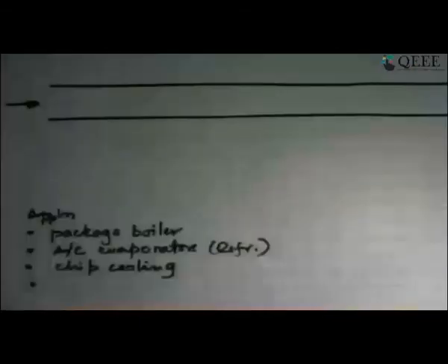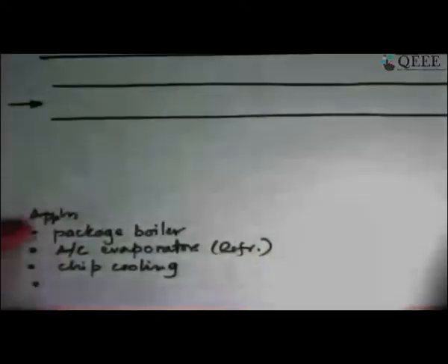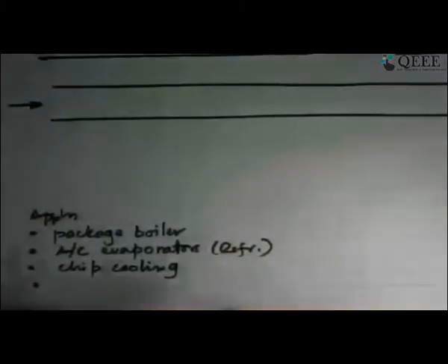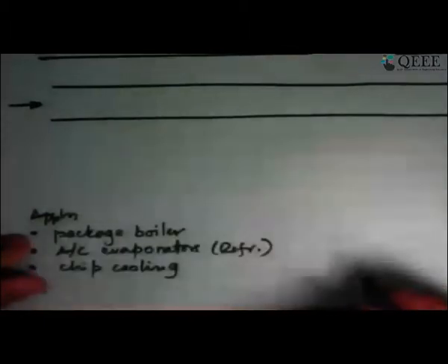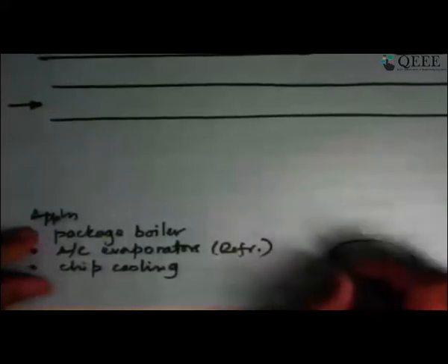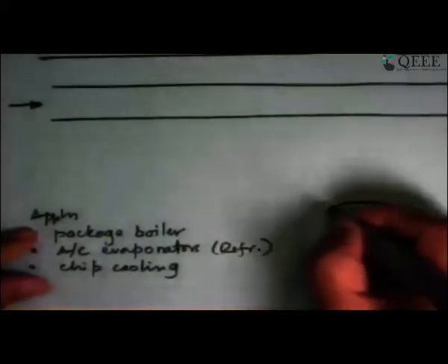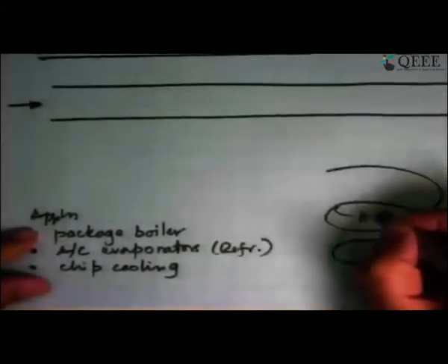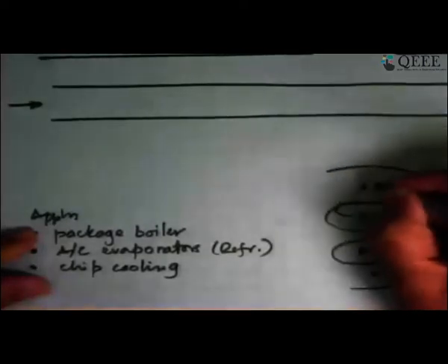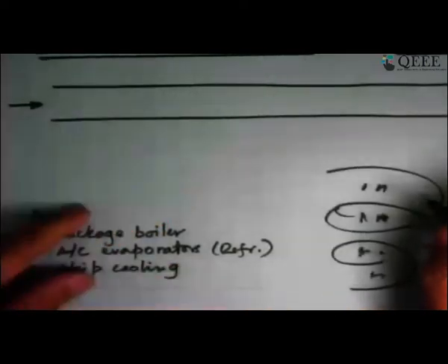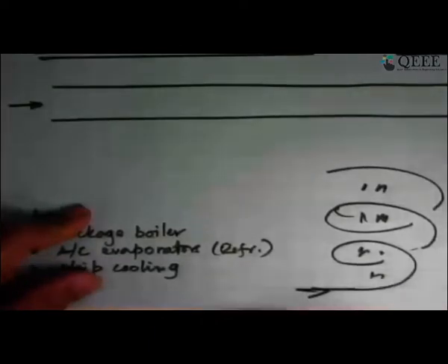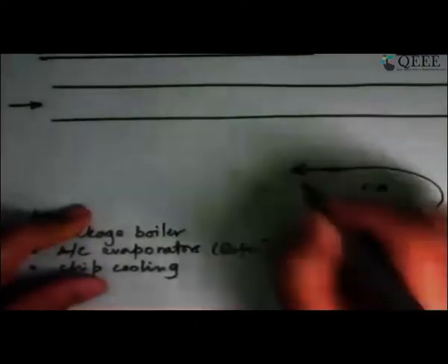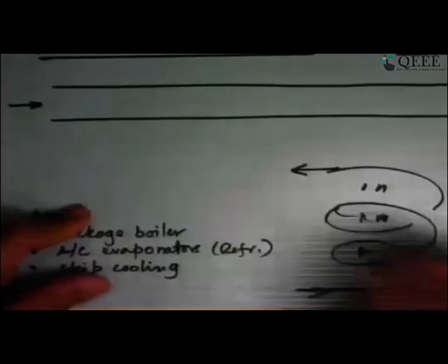And the fourth combination that is now left is internal forced convection heat transfer, which is internal forced convection boiling inside tubes. And where do we see this? We'll see this in a package boiler where you have a tube. I'm just drawing the shape of the tube like this. And inside this is hot. Over the tube, we have hot gases which are produced by burning of flame. What came in was maybe subcooled liquid. What goes out is saturated vapor.